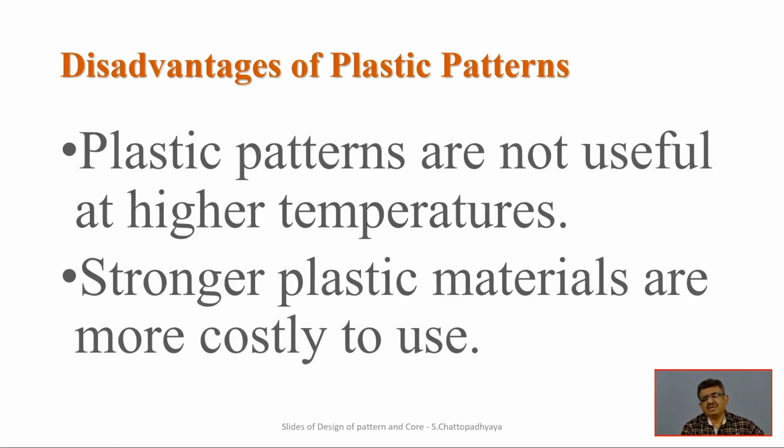And disadvantages are definitely there. Plastic patterns are not useful at high temperature. Temperature sensitivity, temperature related things, are sometimes very uncertain. So, plastic patterns are not useful at high temperature because they will melt. And stronger plastic materials are more costly. So, people always have to keep an eye on the international market and find out how the stronger plastic materials will be available there, and one has to get that for their purpose of delivery.